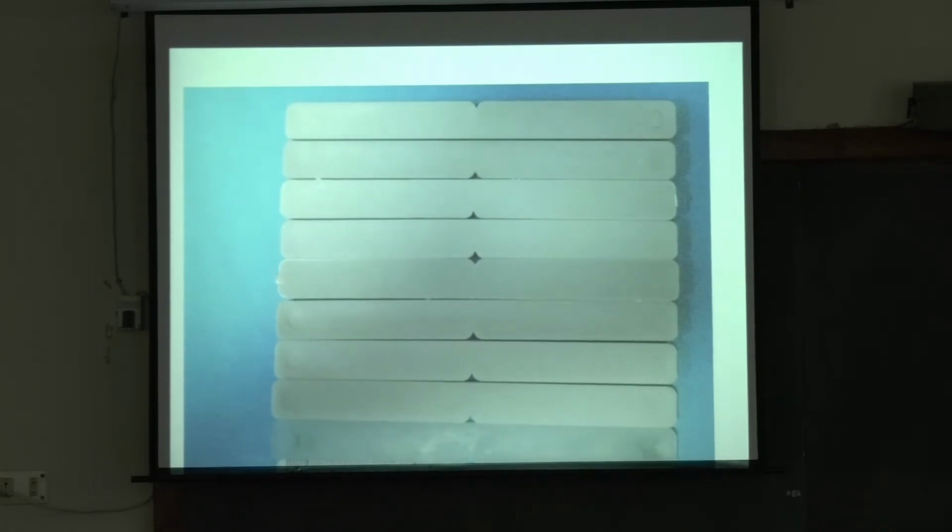So I went there, I stayed for 3.5 months, and I generated all the results on the toughness of those materials. And what surprised them, and me also, was that by using polymers developed from the soybean oil, not chemically, just converting it, and using that as a matrix and then putting glass fiber in it, the fracture toughness became much higher than the plastic and glass fiber materials.